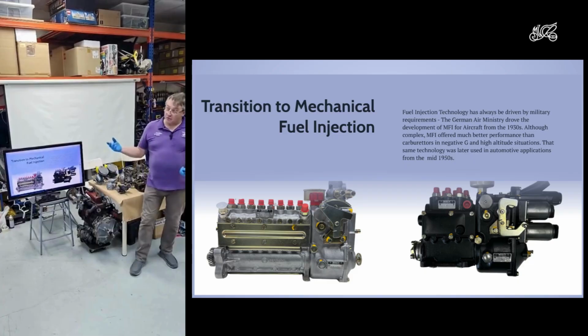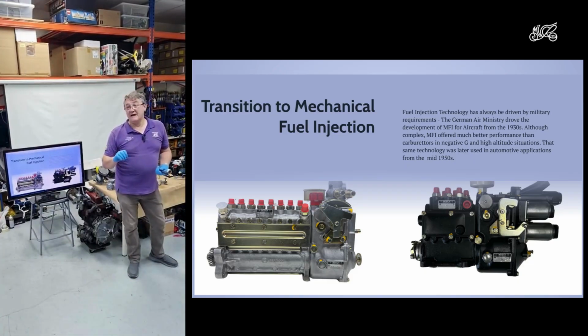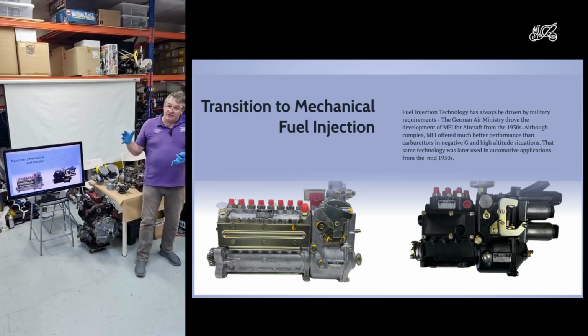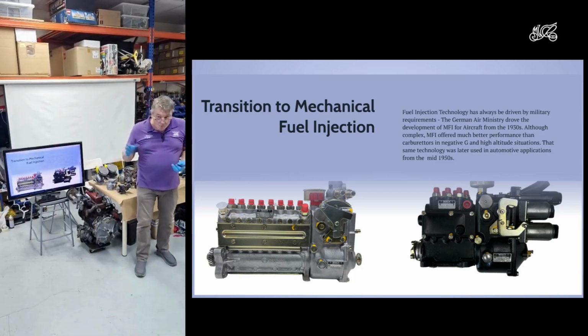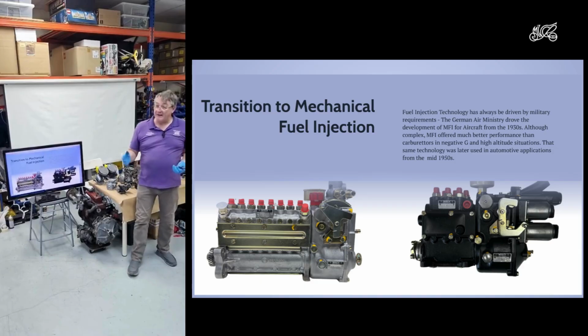As a result, the fuel-air mixture going into the engine is cooler, and that means you get more in, because if the gas is cooler, it's lower volume, so you get more charge into the cylinder and therefore more power.